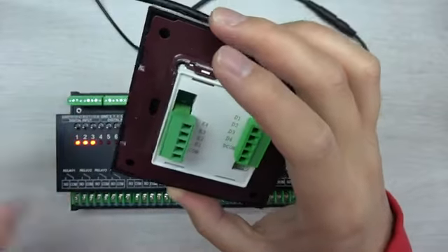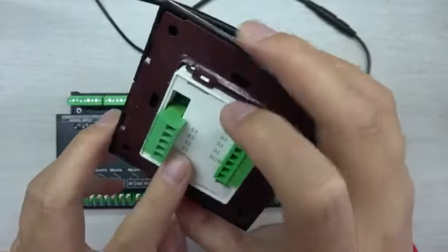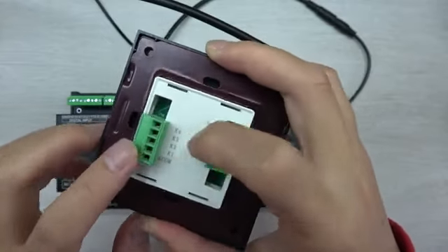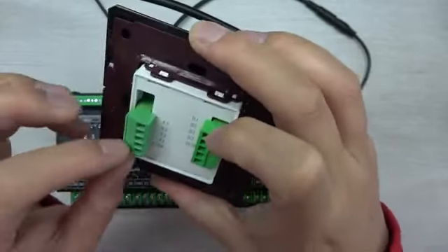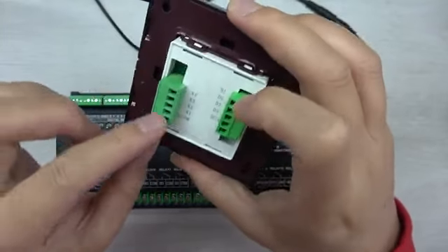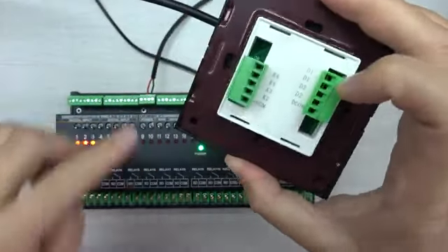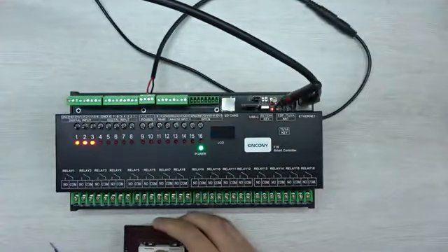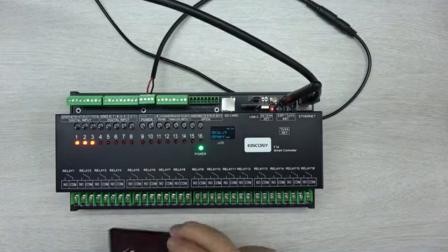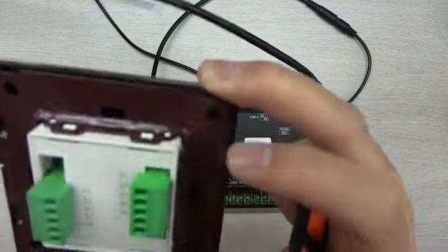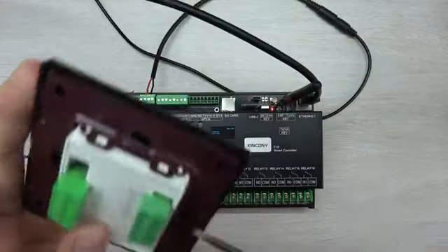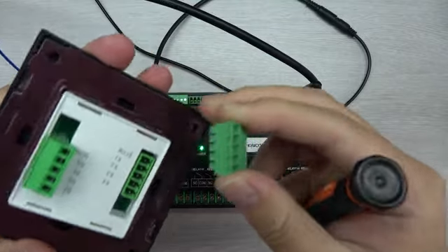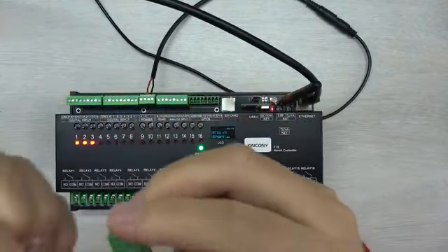And if there is just only one lamp, I just connect with K1. If you have a second switch to control the second lamp, you can also connect with the K2. And the first one, we just do the simplest way. We can connect K1 to digital input 1 and the KCOM to ground. Okay? So I will use the cable to connect it. And this is removable. You can see this is removable, so you can remove it and connect with the cable.